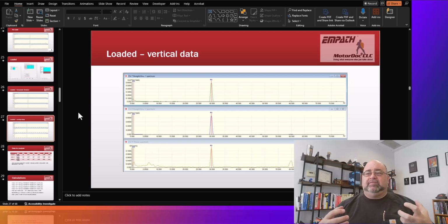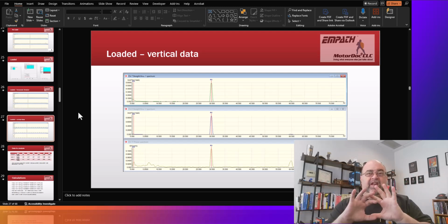And I said, and if you're listening, Chad, borescope. Go in with a borescope and take a look and verify. Always verify. We're using black box technologies with squiggly lines, sometimes video, to try to identify what's going on inside a box that we can't physically see inside.